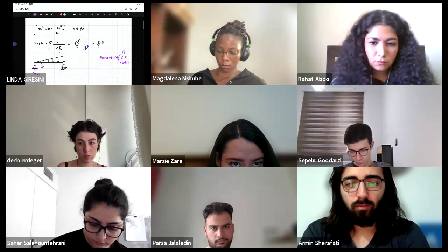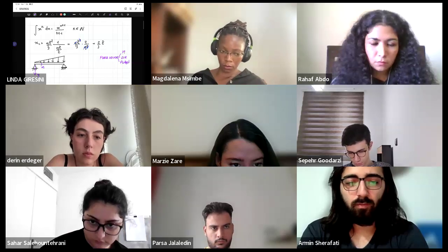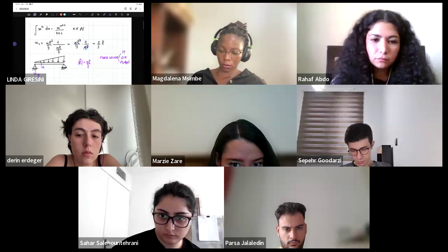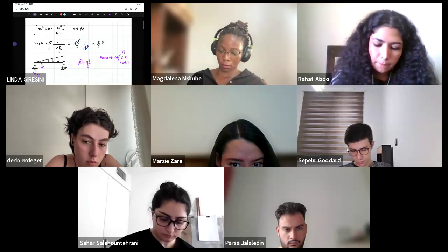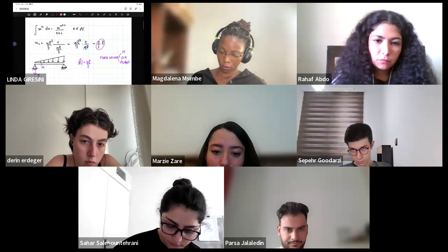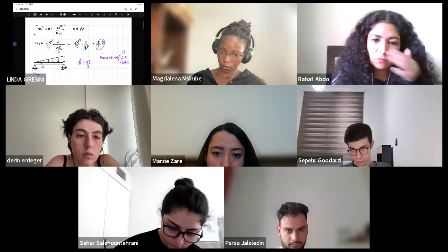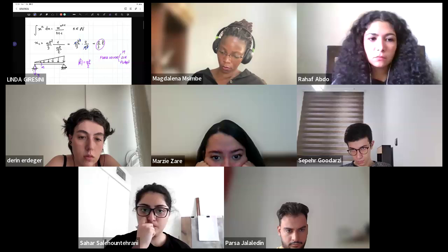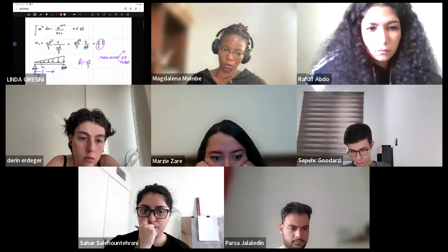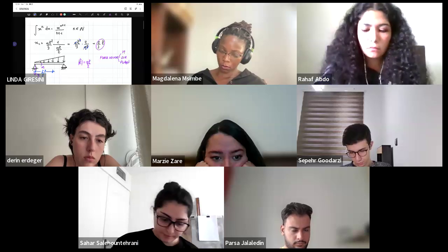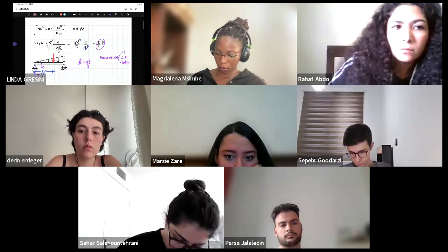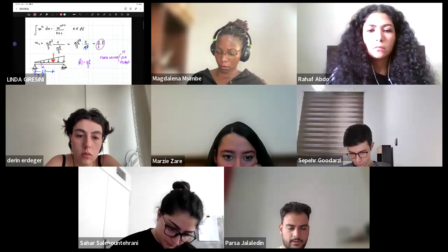So we have the magnitude, which is the resultant. So R is equal to QL divided by 2, which is the area. And the position is at 2/3 of L from 0, so from the axis origin. So you have to check what is 2/3 of L. That will be somewhere here, for example. This is 2/3 of L, and it means that your force will be here. So this will be your resultant force.